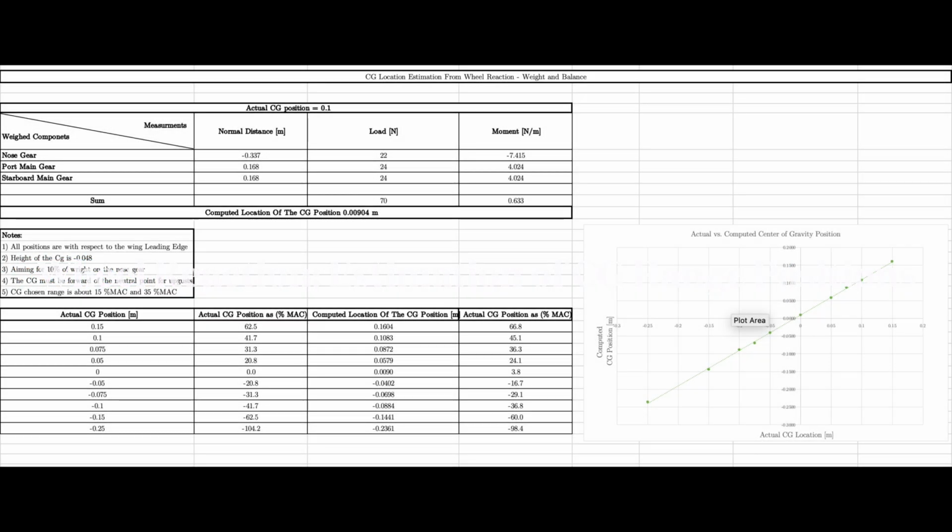An appropriate range of CG was therefore found to be between 20% and 35% of the mean aerodynamic chord, by comparing the analysis findings to elementary moment estimates as displayed. It also should be noted that to preserve aerodynamic stability, by generating a nose-down restoring force against gusts, the neutral point should be set aft of the CG.